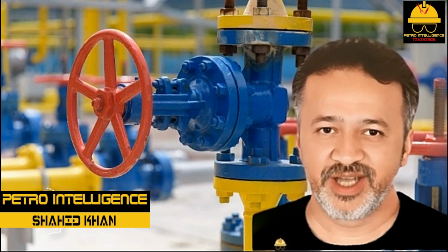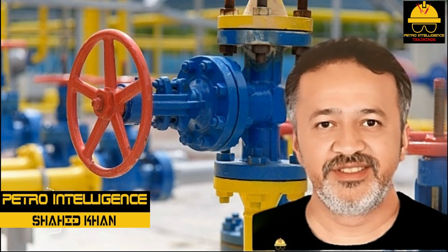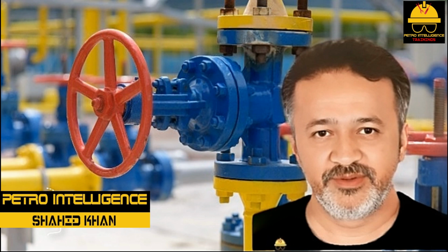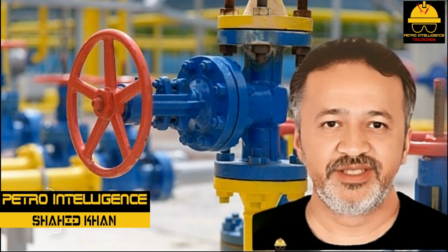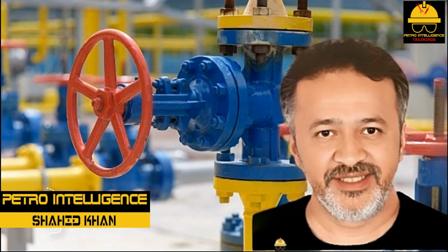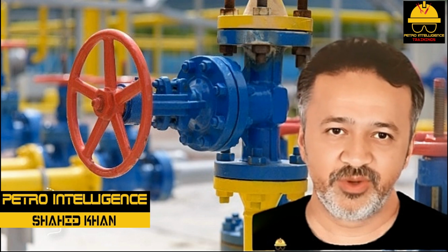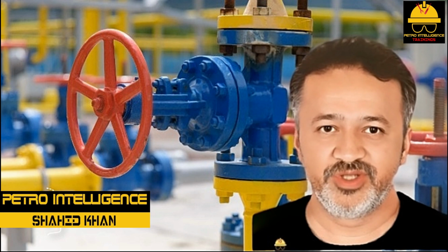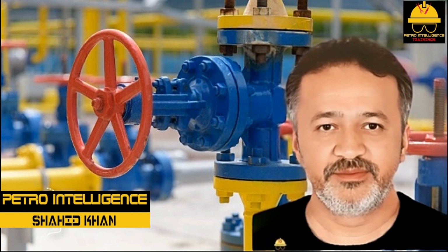When closing a gate valve, the operator should take care not to damage the valve seats. Temperature changes, closing a valve too quickly, and pipe expansion can cause a valve to warp. Because warping can cause a valve to stick, the process technician should close valves slowly. When the gate is on the bottom, a wrench should never be used to snug it down.